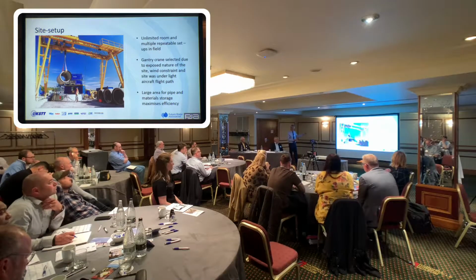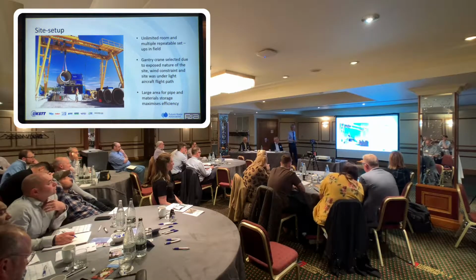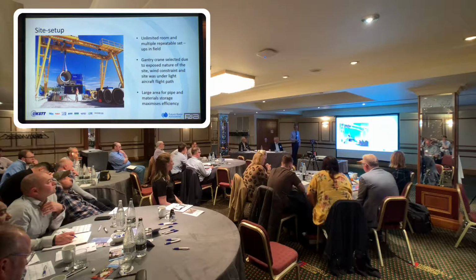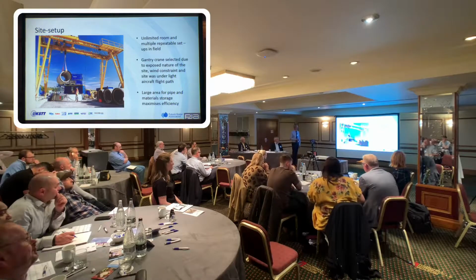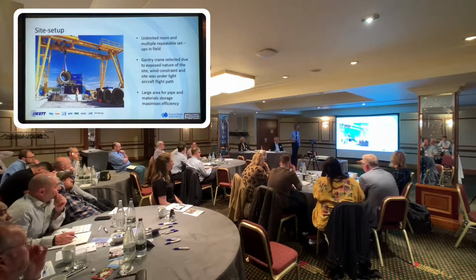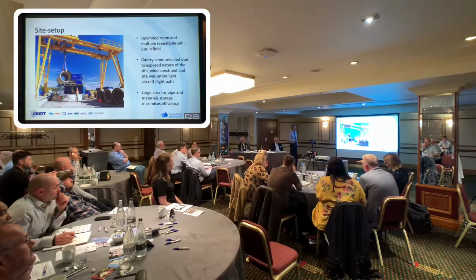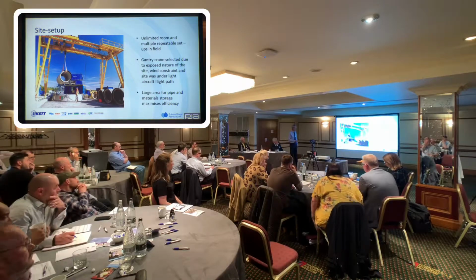So this is, again, a picture of a site in Welwyn Garden City where we have unlimited room, but it's very, very exposed. It was on top of a hill next to a light aircraft facility, and we had wind problems. So one of the ways of mitigating the wind problem with craneage was to use a gantry crane. We could only really do that because the site was very large. It also meant that the planes didn't fly into it as they were on final approach on that particular shaft. But again, you can see the pipe store under the crane, shaft top.